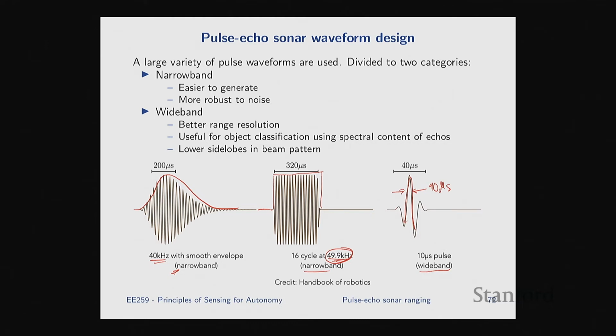Okay, and this is just one pulse. Remember, the way pulse echo sonar works is it periodically sends these. If you look at your time axis, what the TX is doing, let's clean it up, in the wideband case, it's going to send one of those pulses, then it's silent, then it will send another one and another one.